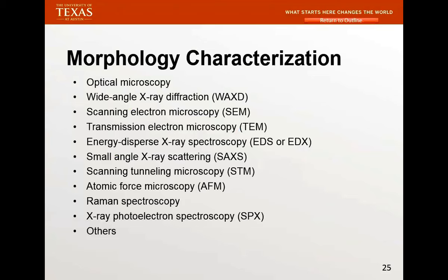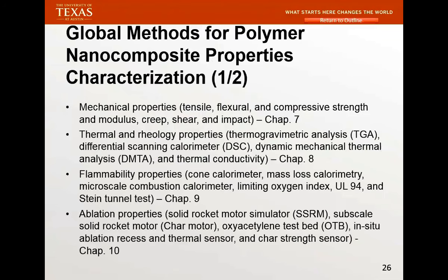TEM is very, very useful, and all these are useful. But TEM can show you directly. This is what I call direct measurement. All the other things you can see are good, but is it really dispersed well? You don't know.